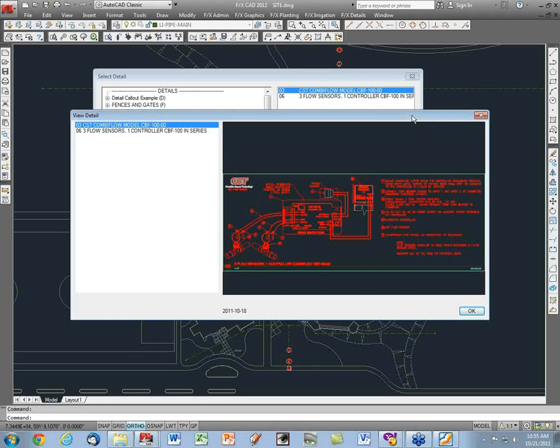What probably my little diagram didn't show was we had a situation where there wasn't enough straight pipe discharging from a booster pump before we went into the T that divided the flow in 2 directions. So we put 2 sensors, one on each side of the T. But no, if it is a loop system and you have the ability to get a straight piece of pipe section before the branch, then that's fine. You'd have a single flow sensor.